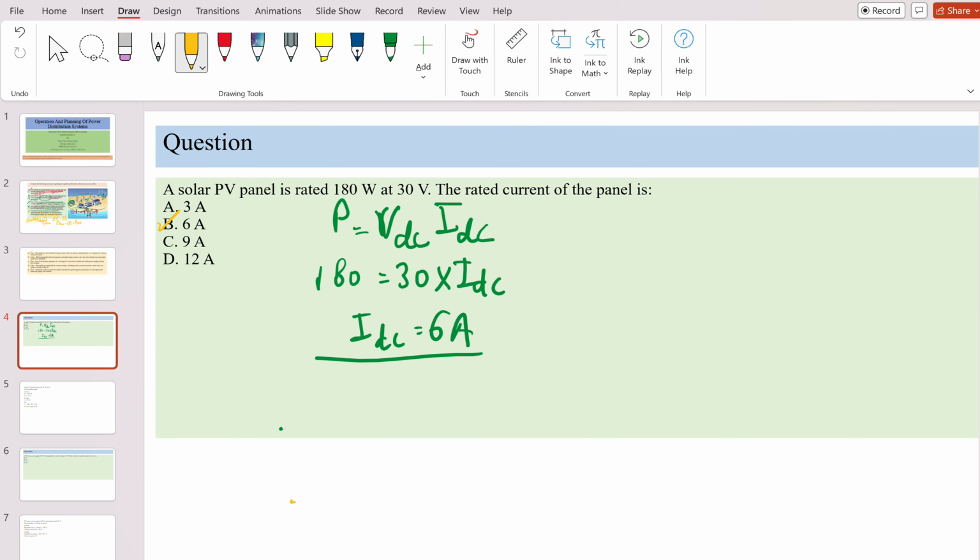When you have solar generation, suppose I have connected a PV plant here, and this is generating DC. This is basically fluctuating DC, and you require a constant DC. So you connect a capacitor in between to regulate the voltage and keep it constant. That is called V_DC.